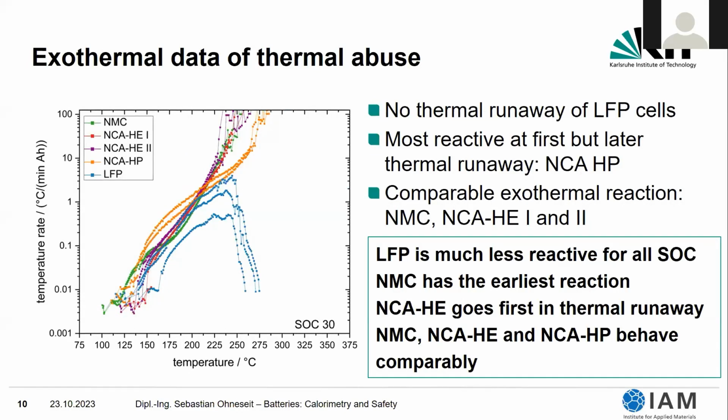To spare you all of the states of charge I tested, the last state of charge I'm going to show you is SOC30. That one is very interesting because that is normally the state of charge where the cells are transported. So this is the one if you want to know about when the next ferry is burning because of electric vehicles. What you can see is that the LFP cells have a much different behavior once again, but in this case, they do not reach a reaction rate that can be considered as thermal runaway. There is a thermal decomposition taking place, but no thermal runaway.